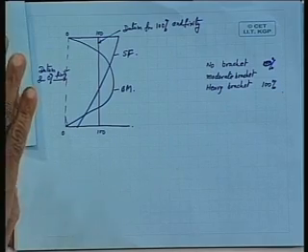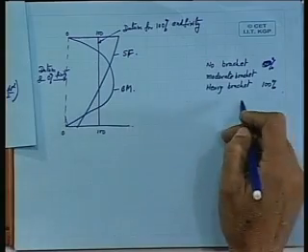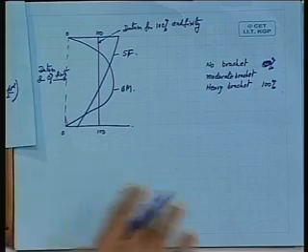Like two cantilevers, you have the deck here and the bulkhead is coming and they are simply welded on the two sides. It will be still watertight. So, that connection I consider it to be no bracket. There is no bracket between the stiffener and the bulkhead underneath the deck. So, that is 0%, and if there is a heavy bracket 100%, if it is a moderate, then I have to make a decision.